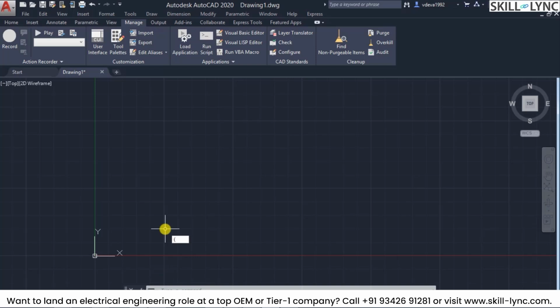Next, you're calling a system command, so you precede that with the command keyword. Then within open and close quotes, you call the system command that you want to do, that is "circle ". Please note the space that we gave in between. After the space, we have to pause for the user input for the center point, so let us give a pause command and a space. Once the pause has come, then now to the circle radius. So 50 is what we want.